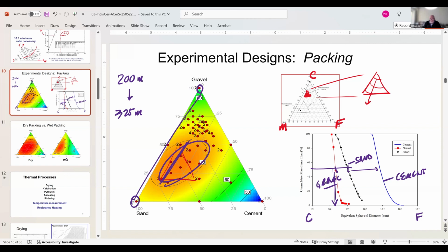And the result in terms of packing is 0. There's no result in packing. This is 75 microns, right? This is 45 microns. This change in size is not enough to make a difference in your packing behavior. So substituting a finer material, there may be other benefits of doing that. The traditional ceramic manufacturers and porcelains took out their 200 mesh quartz and put in 325 mesh quartz, and were then surprised to find no change in shrinkage in their ware coming out of firing. So if you wanted to change this, you have to change this to a 7 micron quartz, which would be very difficult to process, to change the packing behavior of the body.